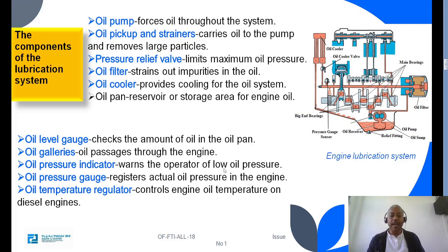Oil pressure indicator: this unit is found on the dashboard and informs the operator of the oil pressure. Oil pressure gauge registers actual oil pressure in the engine. Oil temperature regulator controls the engine oil temperature on diesel engines.